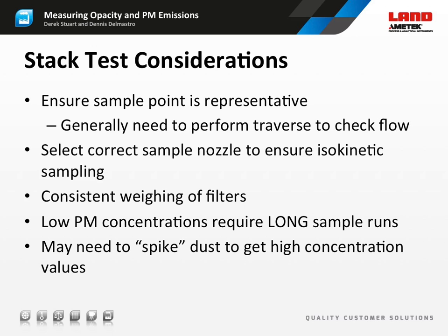Because it can be difficult to generate adequate medium and high-level measurements by changing the process conditions, it's sometimes necessary to spike the sample by injecting fly ash directly into the flue so that it can be measured.